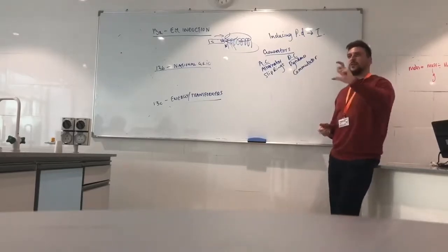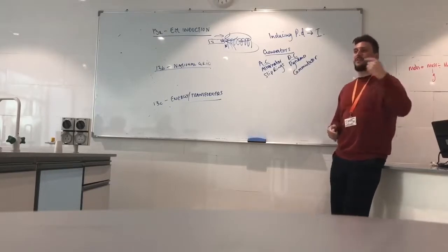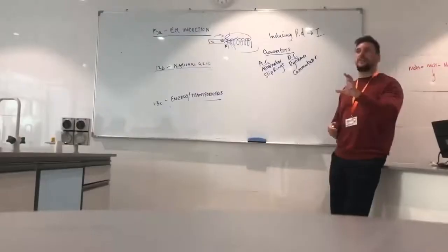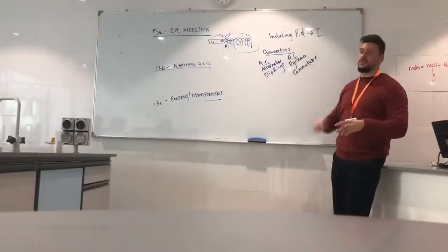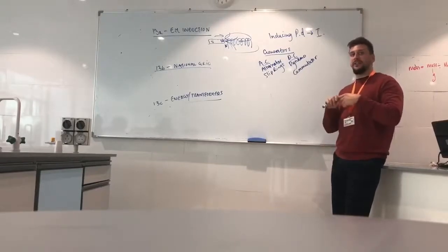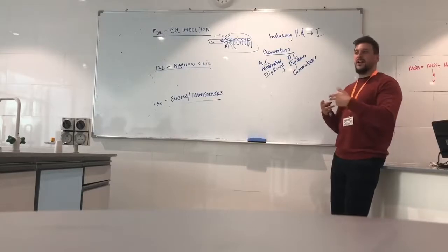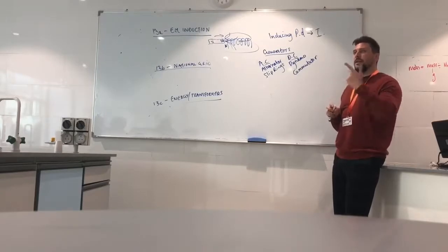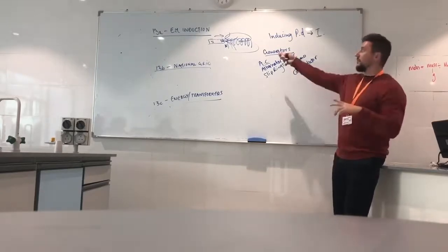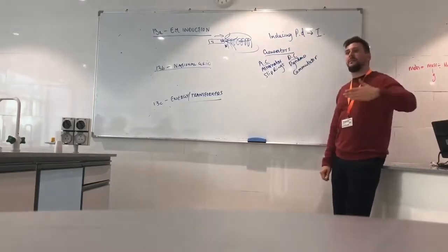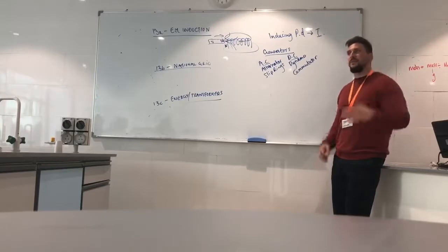When the AC goes to the coil, you have current changing directions in a coil, which means there is a magnetic field induced in the coil, like a solenoid, in a changing direction. What happens is the motor effect occurs, and the coil moves again because the coil's magnetic field interacts with the permanent magnet inside the coil. Because the current is AC, the magnetic field produced is AC, and therefore the motion is forwards and backwards, moving the diaphragm of the loudspeaker forwards and backwards and amplifying the sound.